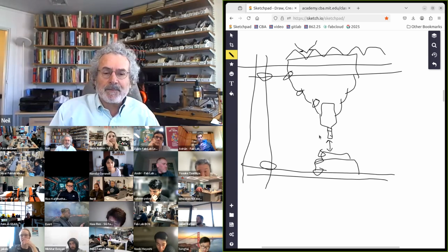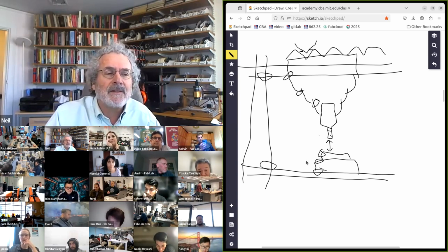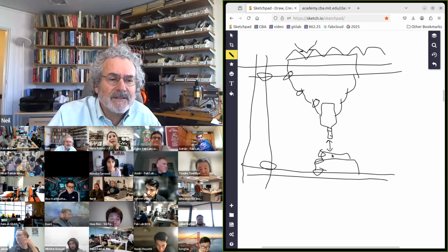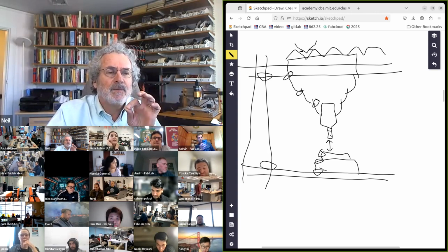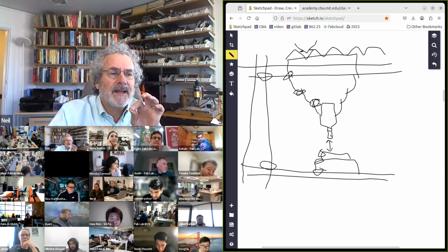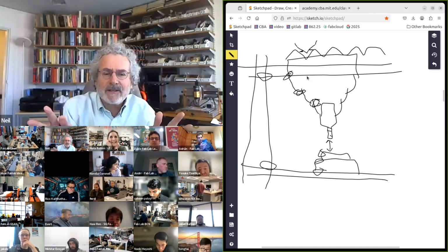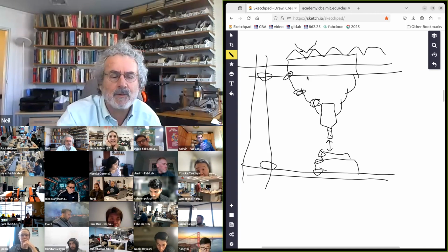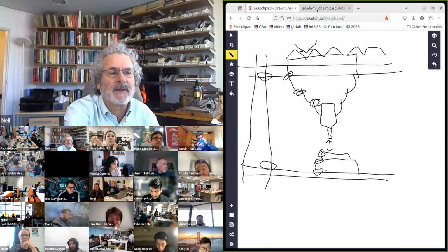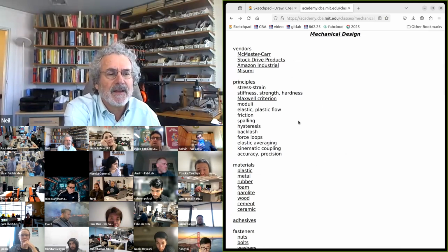So to design the machine to make this tolerance tight, we need to understand the errors in the whole force loop. And in particular, we want to minimize the force loop to minimize that error stack up.